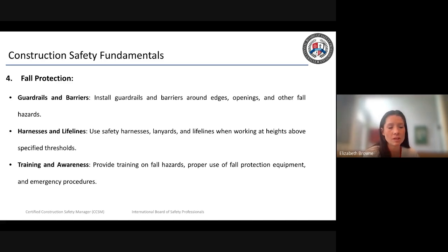One of the biggest challenges I see on construction sites is ensuring that you have anchor points for the fall arrest systems that are sufficiently rated, and have been rated by an engineer to state that they can withstand the forces of a fall from a person. Typically those forces are going to depend on the fall height, and those calculations will need to be made by that competent fall person.